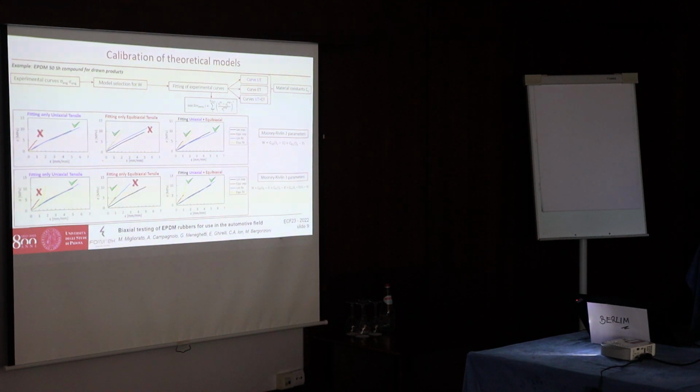We use ANSYS Workbench as a finite element software. We have checked the different models available in the material database, but I have not found microstructure-based models to define the strain energy density function. There is, for example, the Yeoh model, which is again phenomenological.